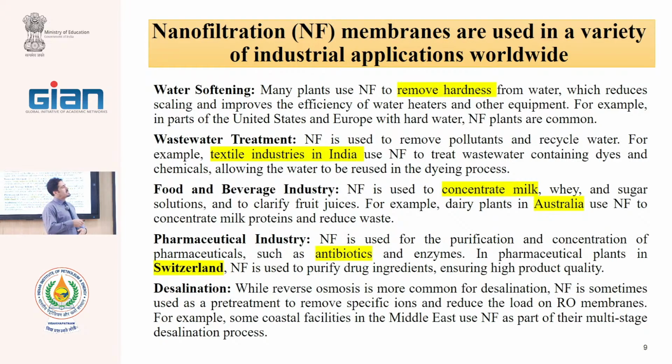Therefore, most water supplying companies use well water, and for removing the hardness, calcium, magnesium, usually use nanofiltration because the concentration of NaCl in well water is very low, okay?